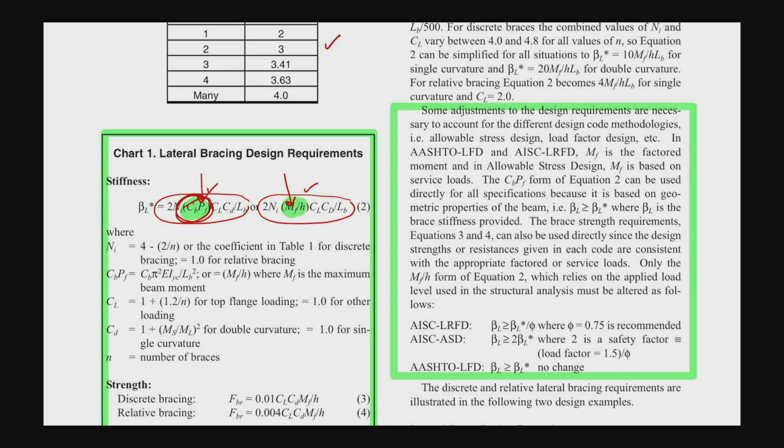Regarding that fact, this will be very conservative. The lower the unbraced length spans, the more extremely conservative this is going to be. But with this one, you get the MF, and the MF incorporates the inelastic buckling, as the MF comes from the beam lateral torsional buckling limit states listed in the flexure chapter. So this one is supposed to be lower. Should I call it less conservative? It is still conservative, but the other one is more conservative.